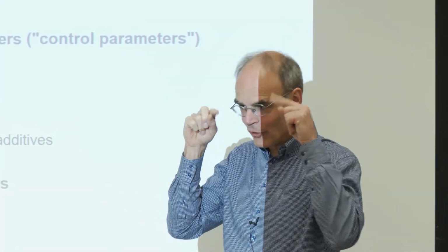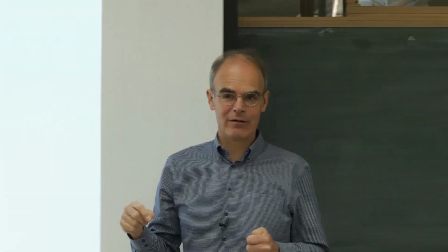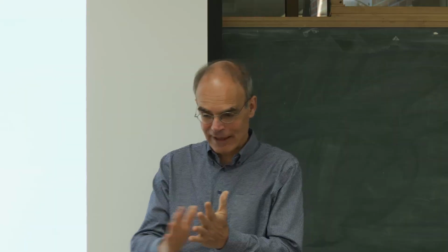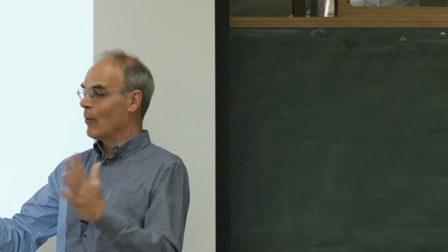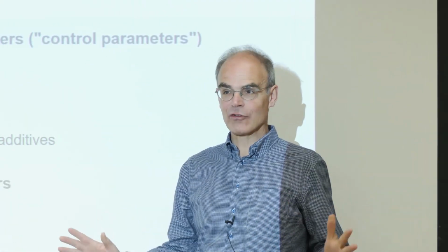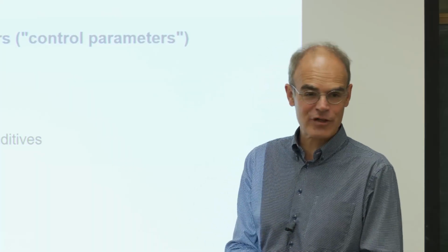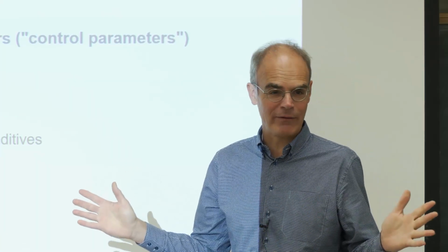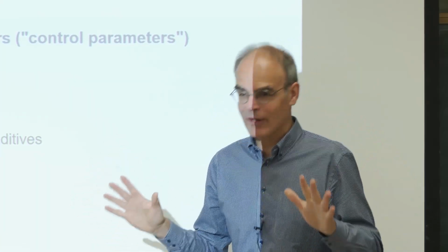Yeah, and it's just because of the misinterpretation of the water content. I had calculated on one basis, without this. We had no prior discussion. We just came in, we're starting the extruders, and then bang, there it went. So yes, you can damage extruders.